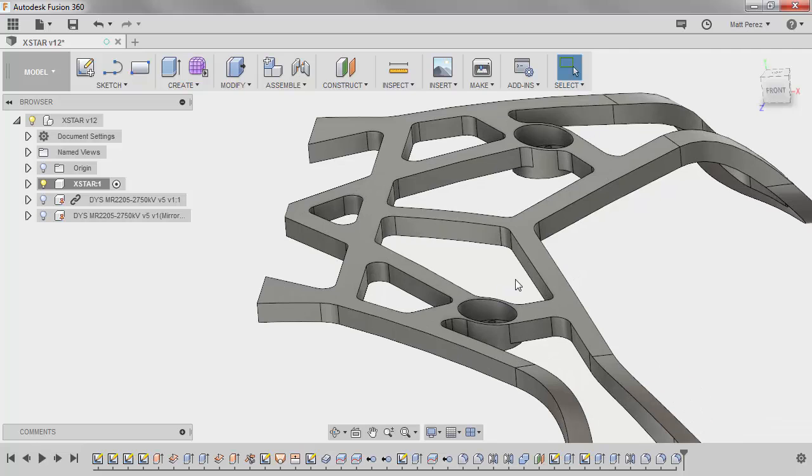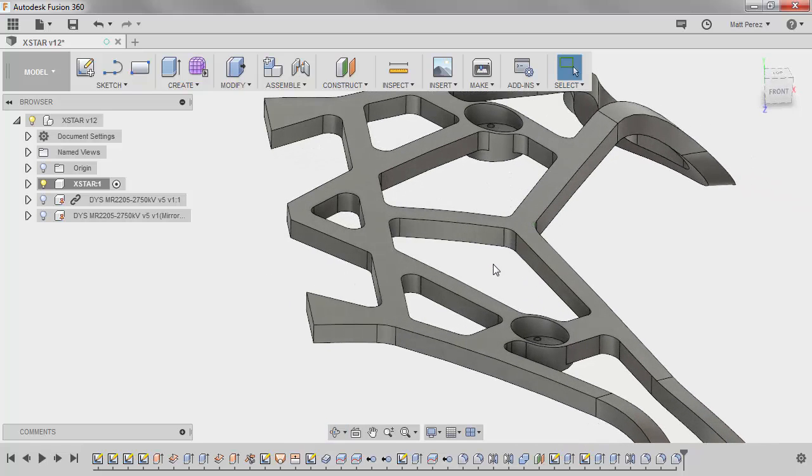And again, these are all areas that you have complete control over. The changing of the radii on these corners isn't going to affect the overall process. At this point in time, we need to make sure that we do have rounded corners just because of how the stress is going to be concentrated on the plastic part. We want to make sure that everything is nice and smooth and rounded.